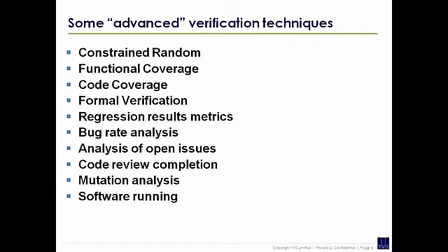It never runs fast enough to run software. So a lot of people here will map onto an emulator, which is very expensive. One of the advantages of being in the FPGA world is that you can run at speed. You can actually run software very early because you're running on FPGAs, which typically run at megahertz, which allows you to run software properly.